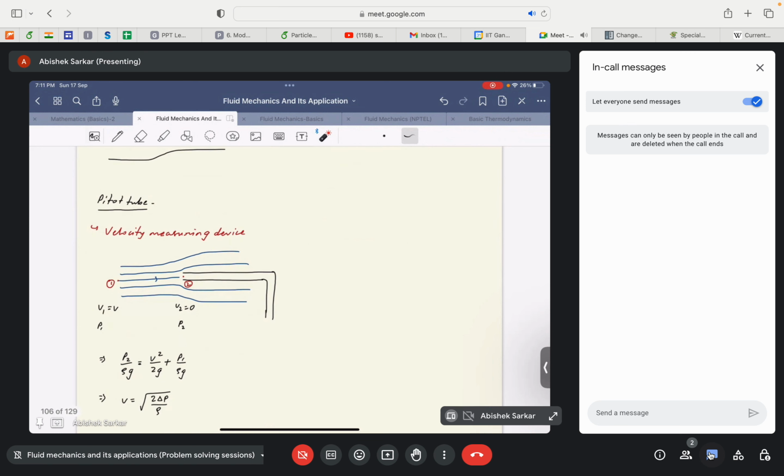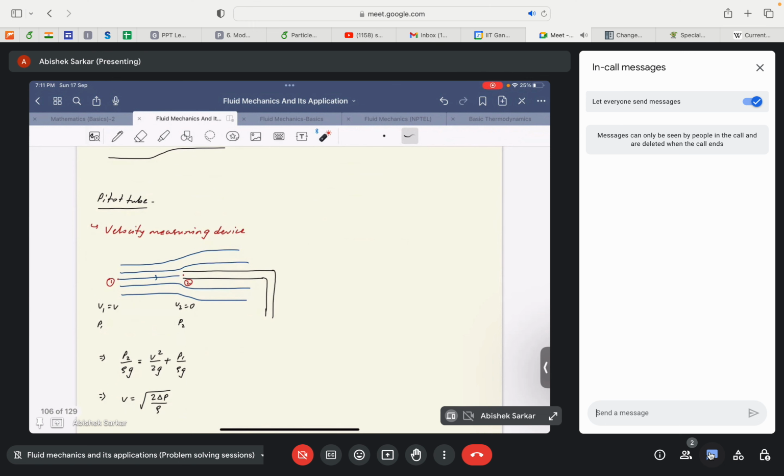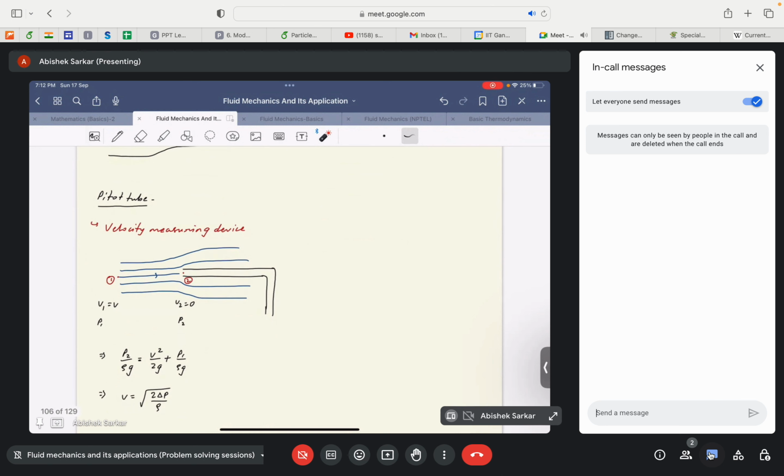Here you will see the functioning of the pitot tube. There is usually a bit of confusion among students on the application of pitot tubes, venturimeters and orifice meters. So I would emphasize that the pitot tube is a flow measuring device which is used to measure the flow velocity. This question usually comes up in many competitive exams and in interviews.